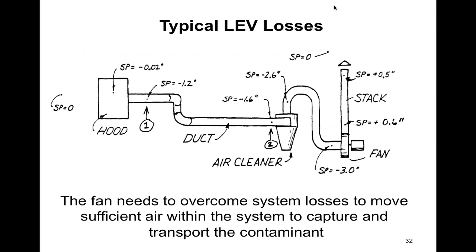To give you an idea over here, the fan is down at the end. The static pressure, remember that suction pressure? That's what's driving stuff here. Static pressure is minus 3 inches at the fan. In other words, it's sucking so hard that if we put a hole in there and put a tube up on it, it would support a 3-inch column of water.